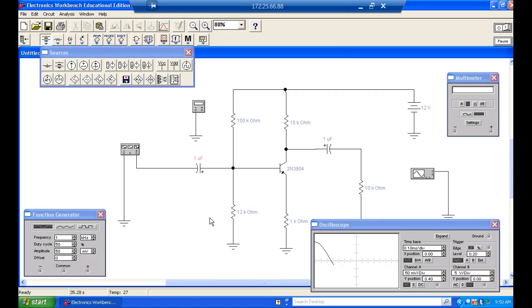No, the base voltage should go to 0. It's going to drop to 0, or pretty dang close to it. Now it all depends on the input impedance of the actual source itself. Yeah, but it's microvolts. Microvolts on a meter looking at DC is nothing, right? You understand that? So yeah, it went down to 0, which is going to cause the transistor to do what?